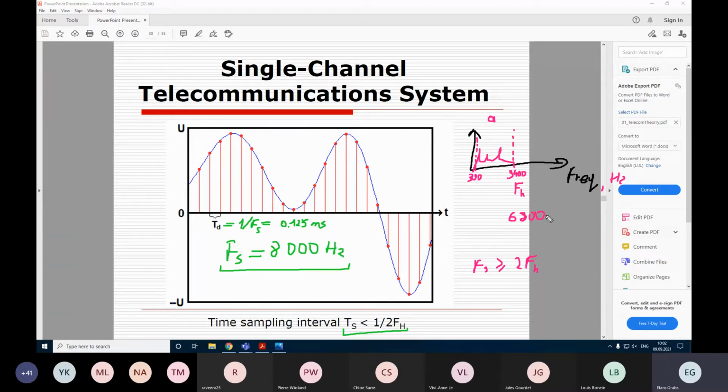However, there is one more thing we need to take into consideration: in real life, the spectrum doesn't really end here. Something is also there. This is just insignificant information which can be skipped, but it can still interfere with our signal and degrade quality. So for that reason, we need to use a filter. And filters, sadly, cannot be implemented with a sharp cutoff frequency.